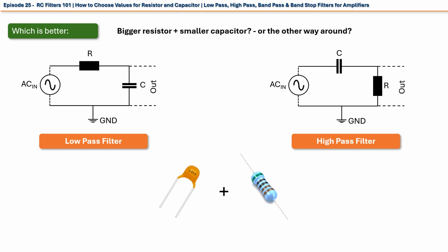For example, a ubiquitous 104 capacitor, with 0.1 microfarad capacitance, can vary anywhere from 50 to 150 nanofarads. This is a pretty big and unacceptable margin of error. For smaller capacitors, the situation worsens. On the other hand, even the cheapest resistors have a smaller margin of error, around 1 to 5% of their declared value.